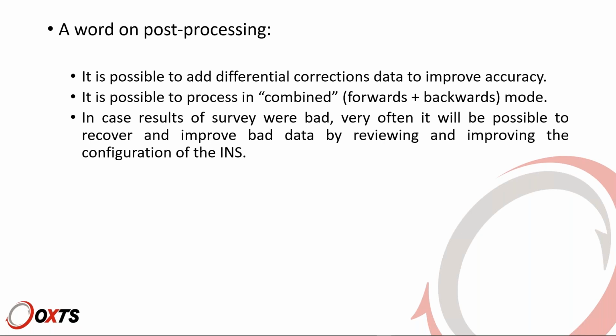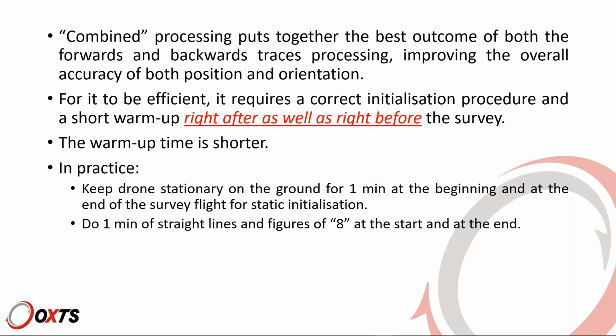The only thing that is not possible to change is the raw data that the system will have logged, so GNSS data and inertial IMU data. Once it is logged, this is it. You can't change the number of satellites that you were tracking. You can't change the level of accelerations that were logged. But what you can change through the config is how the system will interpret this raw data and make sense of it.